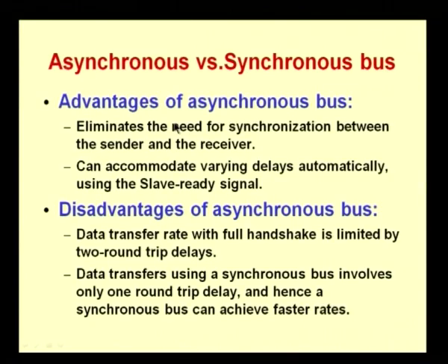So, if you do a quick comparison between the synchronous bus and the asynchronous bus, there are certain advantages of the asynchronous and certain disadvantages as well. What is the advantage of the asynchronous bus? It eliminates the need for synchronization between the sender and the receiver, that is, having a common clock and doing the synchronization with respect to that common clock. That is avoided when we go for an asynchronous bus.